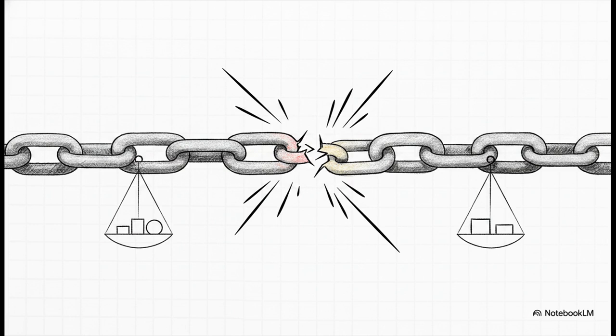So if your rivet can hold 1,000,000 pounds, but the plate tears at just 1,000 pounds, well, your efficiency is terrible. Real engineering is agonizing over every single variable, the rivet diameter, the plate thickness, the pitch between holes, until the strength against tearing is perfectly, beautifully balanced with the strength against shearing and crushing.